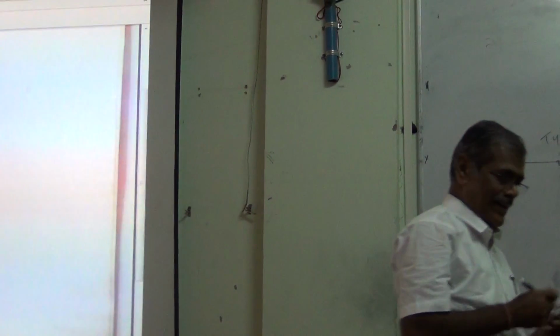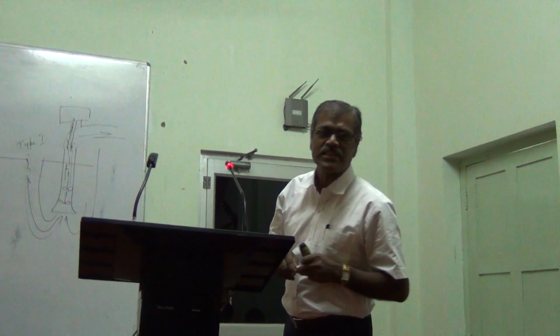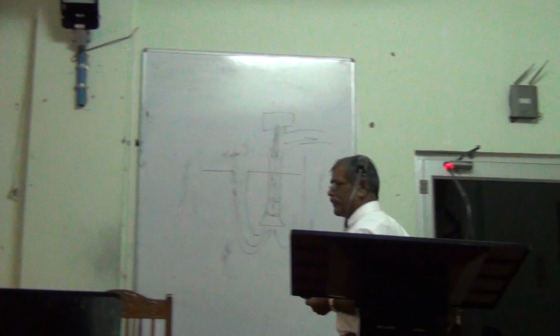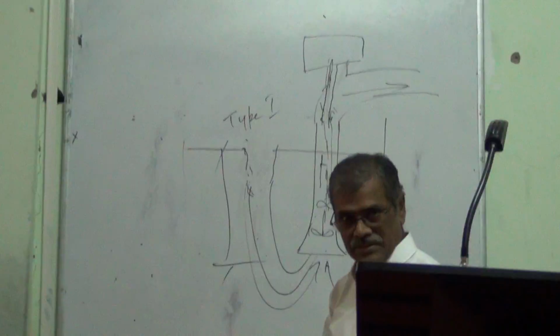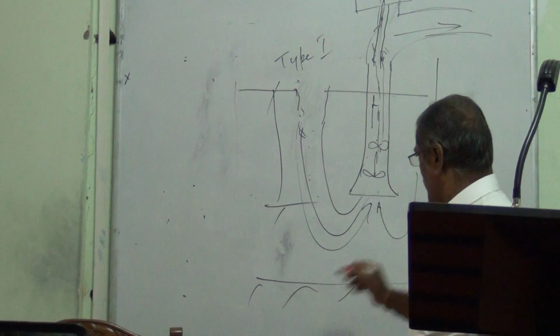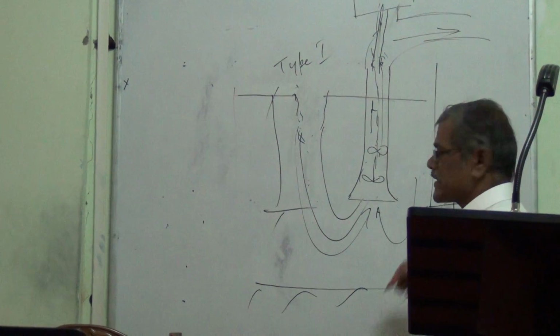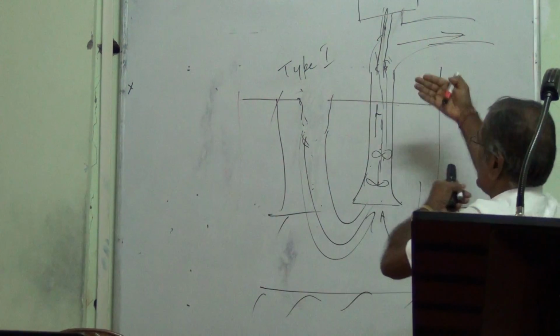So there are certain codes in the Hydraulic Institute, HI, America, or BHRA, British Hydromechanics Research Association, which say what should be the submergence. If this is the floor, what should be the disc clearance? What should be the, this is one section, then one after the other.